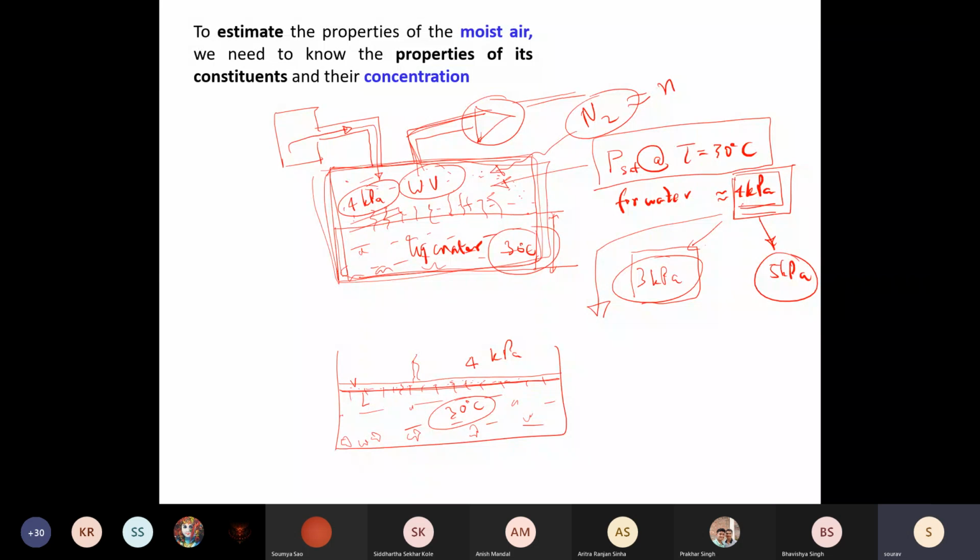During the evaporation, it is just the process happening at this liquid vapor interface. If you try to remove or suck out vapor from this interface, reduce the partial pressure of water vapor here, the liquid right next to this interface will move from liquid and replenish that vapor layer. But when will you start to see vapor bubbles coming from beneath, well below the liquid vapor interface?